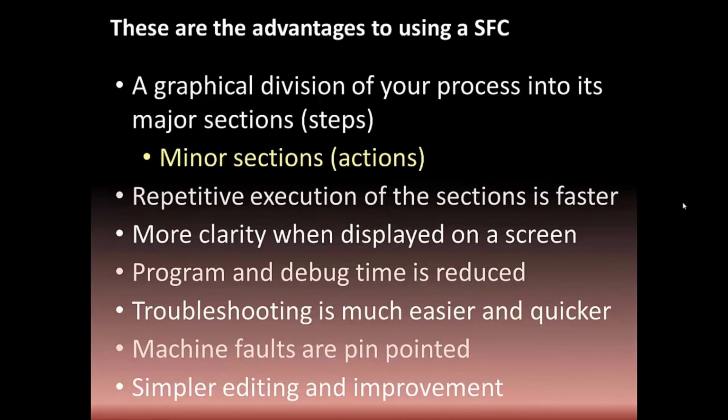Program and debug time is reduced because if you're working with a 1,000 rung program, a ladder logic diagram of 1,000 rungs, you burn up quite a bit of time navigating to the different sections. With a sequential function chart, it's much simpler. Also, debug time is reduced because you typically debug one step at a time. Once the steps and the actions within the step are debugged, then the organization of the steps is a very simple editing process. And of course, troubleshooting is much easier and quicker for the same reasons.